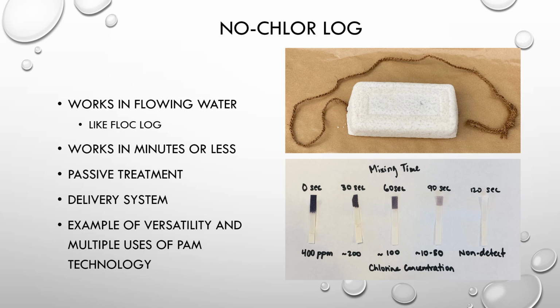Again, it works in flowing water. The mixing and reaction isn't as important as it is to form floc, but we still want to make sure that the materials are evenly distributed and reacting with the chlorine in the water. It works in minutes or less. We need a little bit more mixing time depending on what your initial chlorine is.